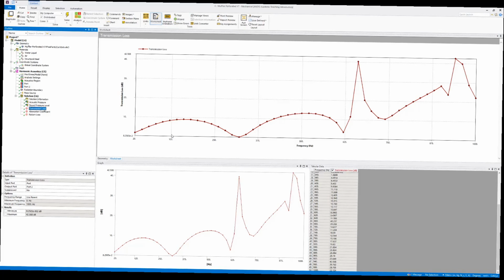So if you have a combustion cycle where you have one combustion per revolution, you'll have 100 hertz at the redline range of where your car is operating. But most vehicles are, say, 4 cylinders, which typically means 2 combustion cycles per revolution.